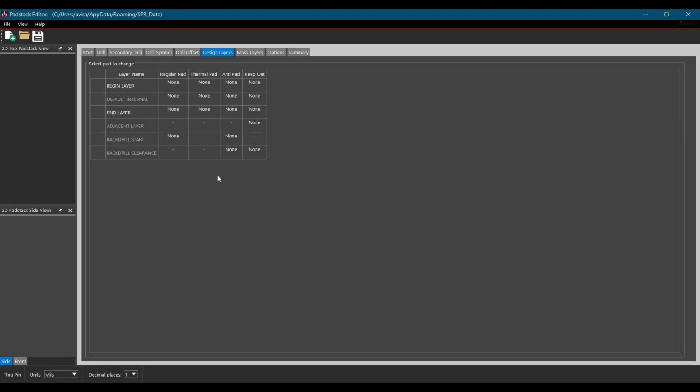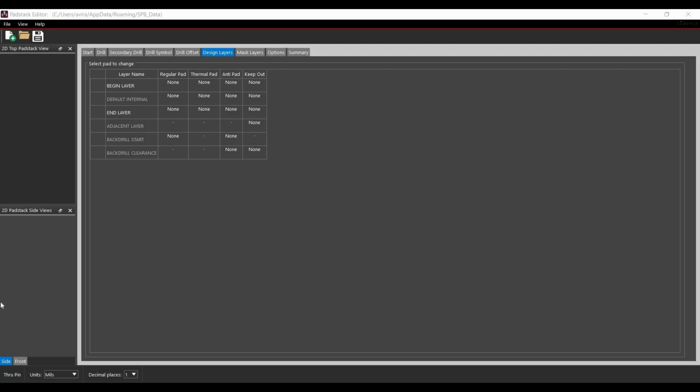Although we have already discussed design layers, if you compare this tab to the SMD Padstack design layer tab, you'll find a few new layer names are enabled. So you'll get a better idea about these extra layers when we demonstrate a through-hole pad. So let's move to a demo of through-hole Padstack for OPAMP LM741 which has an 8-pin DIP package.